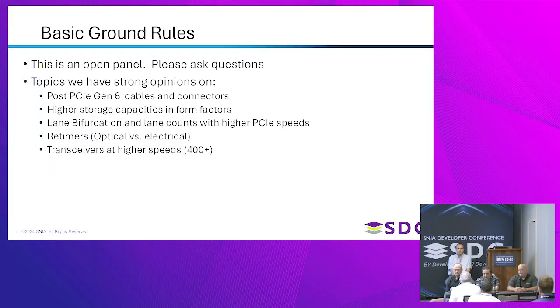My company, Amphenol, has a variety of MCIO connectors, some of which are part of the SFF-TA-1016 specification, and that's what PCI SIG uses for their Gen 5 and Gen 6 copper link internal cable specification. The internal will work for Gen 5 and Gen 6, but the externals for Gen 5.